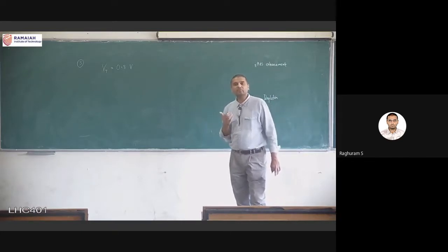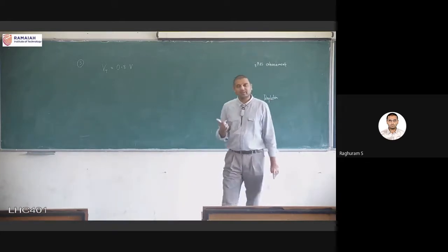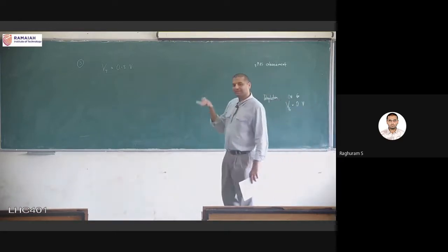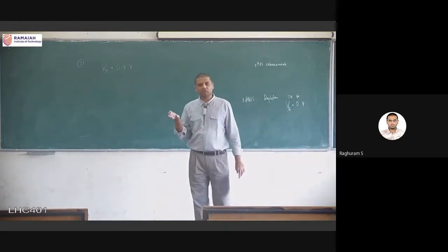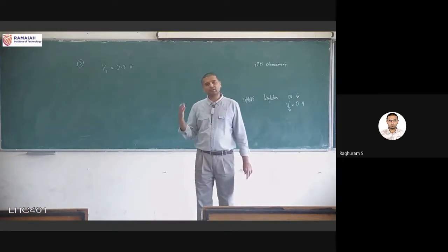Then how do you turn on or turn off the transistor? So in that case, the NMOS depletion transistor is on, because the channel is already there. We don't need the gate voltage to attract any electrons and form the channel. The channel is always there. So even if I don't apply a gate voltage, the transistor is on.